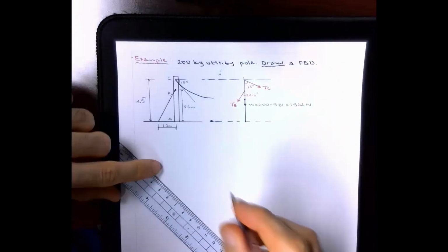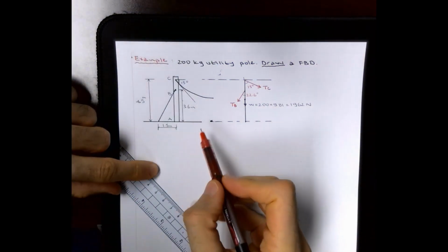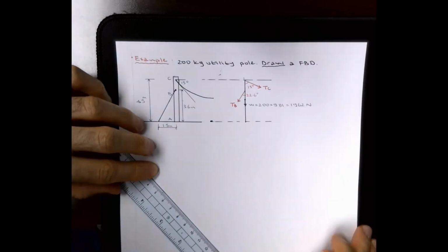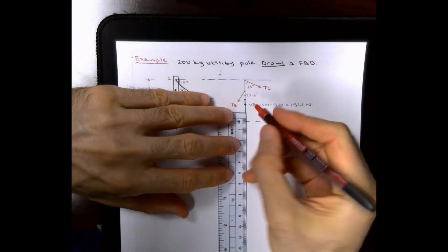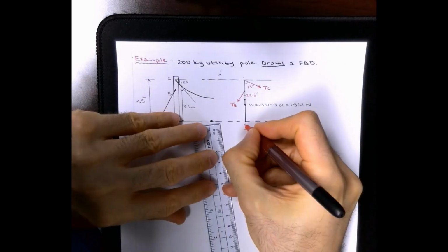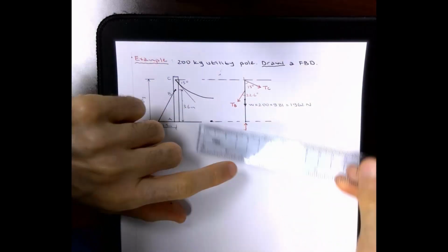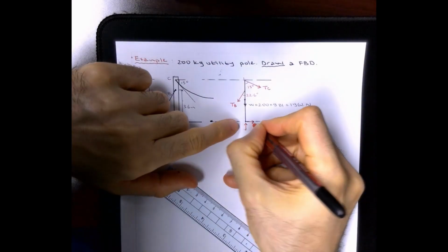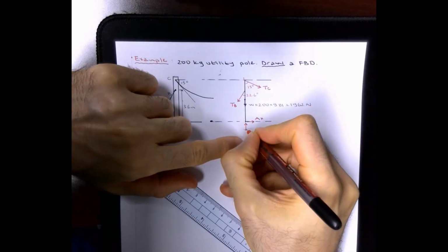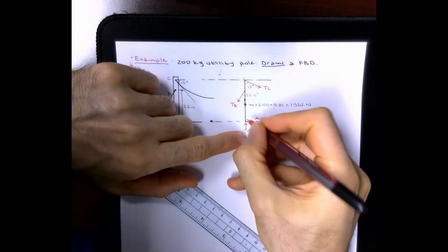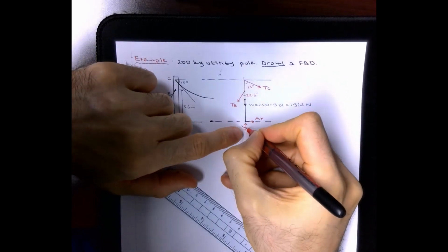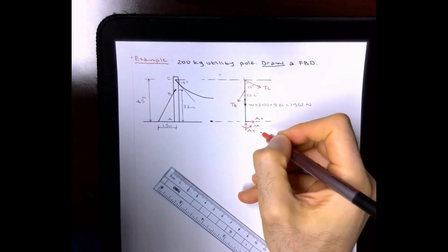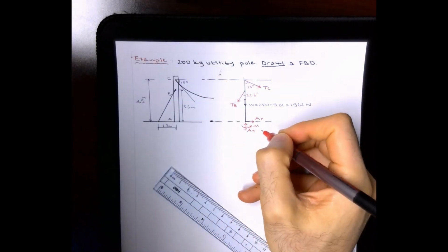degree. And for this pole to be stable, this has to be a fixed connection, and there's going to be 3 support reactions at that point. So I'm going to show. We are not going to find it. If we want, we can find it, but not in this question. So this is AX, this is AY, and don't forget the moment, because it's a fixed support. We covered it on Thursday, and moment. So yeah, that is pretty much it.